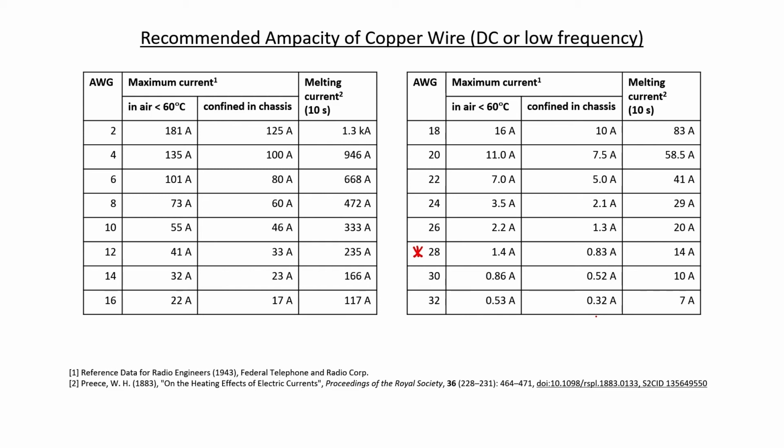There's one more thing I wanted to point out about wire gauge, and that's what happens when the wire gauge numbers get lower than 2, or when the wires start to get really large. The numbers go 2, then 1, and then 0, and then rather than stated in negative numbers, they start piling up zeros. So they have AWG 0, and then AWG 00, which is sometimes called aught or double aught wire. So if you see a lot of zeros as the wire gauge, that's super thick wire.